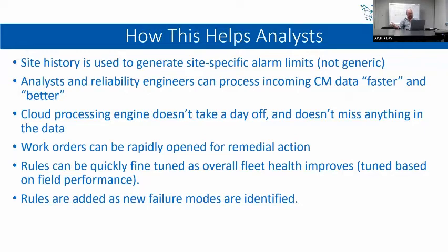We're just band-aiding it. So the system allows the user to easily see that, hey, look, with the time and condition reports, we've had this issue for 3 consecutive samples. We've not rectified it. All we've really done is just change the oil. Hey guys, have we had a good look at this to identify where the dirt is coming in? And let's get on top and fix this issue before it results in component damage.